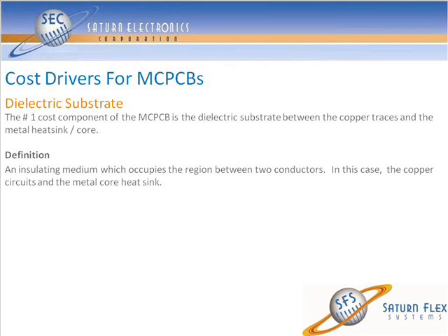If you take a look at your construction, it's all available on the market. You've got aluminum, you've got copper foil. And if you look at the cost of some of these 18 by 24 panels, do the math. You might be talking about $8 to $10 for an .062 18 by 24 aluminum. Copper foil is 80 cents. What are you paying for your raw material? $45, $55, $60.